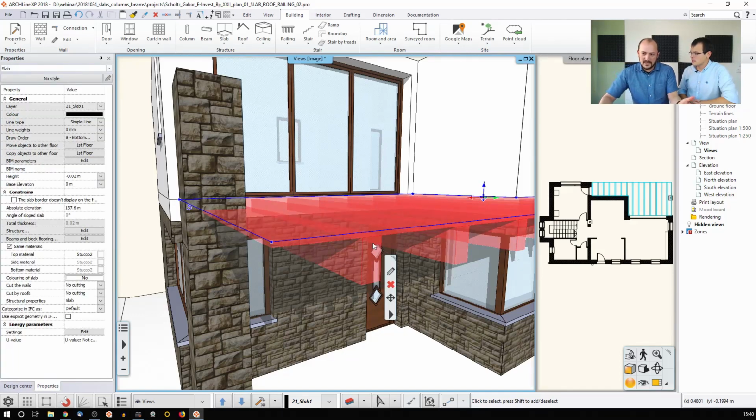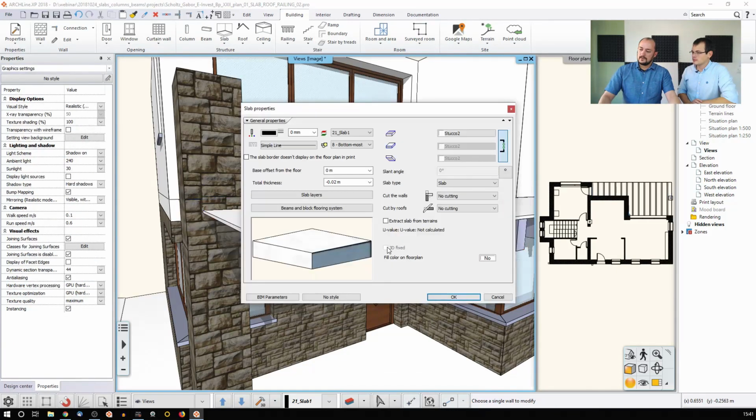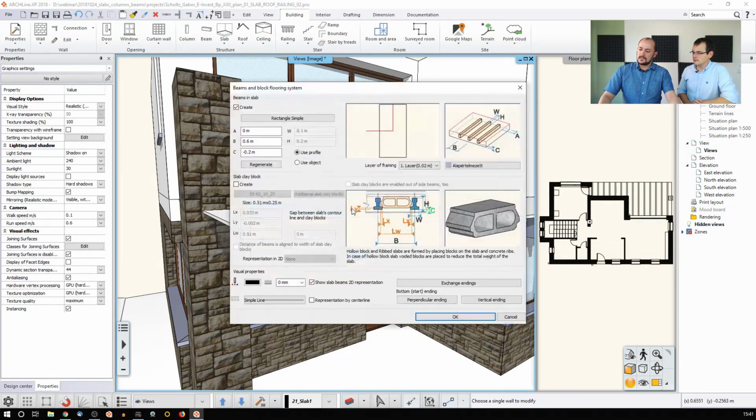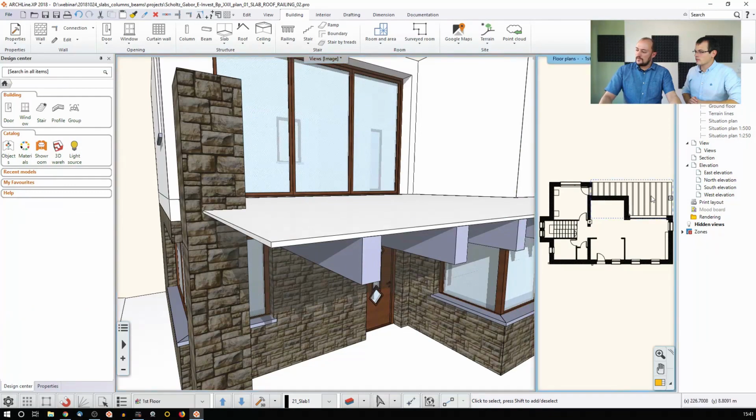Well, there are many ways. This is one of the recommended ways of solving this situation, because now I'm using it in a built-in manner. And talking about the beams, there are two other options that I should quickly cover. One is the span direction. If you select this and say, I'm about to change the beams and slabs, I cannot see what determines their direction, and it's something that you can find here in the local menu of this slab.